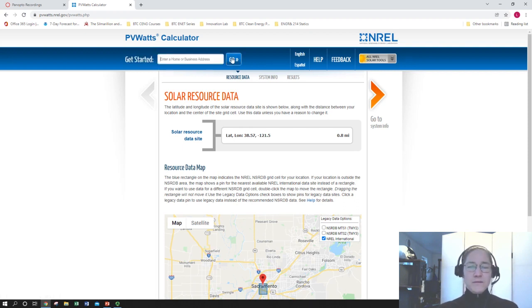So the 4.5 to 5 kilowatts of DC photovoltaic module generation would be your starting point for how many modules you buy. You would look at the kilowatt rating of the module and do the math and maybe buy a number that would allow you to put them in the proper series or parallel configuration to match whatever inverter you had.